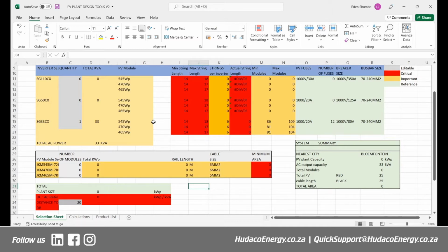What it means is you can put more in a string of the 545s, but you easily reach the limits of the total kilowatts peak because of the size of the panel. So that balance must be investigated very well when you're doing your design. You must investigate it very well to say, okay, it has lower voltage, I can put more of it in the string, but the wattage quickly adds up.